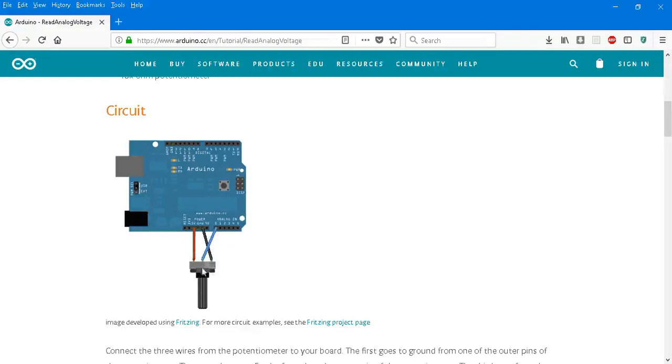And as you know, with a potentiometer, there's a kind of slider in here, or a wiper. If the wiper is towards this side, then 5 volts will almost be flowing through your potentiometer. If you move the slider by turning the spindle, it's closer to the 0 volts, so your voltage will go down.